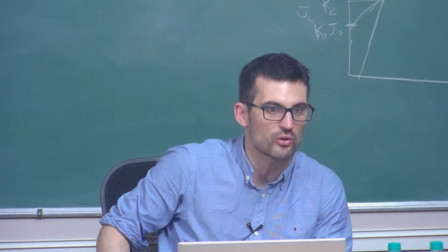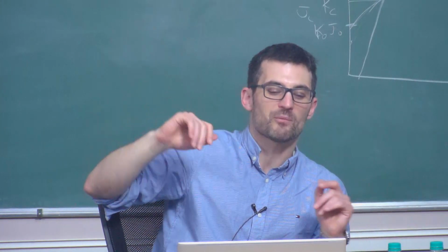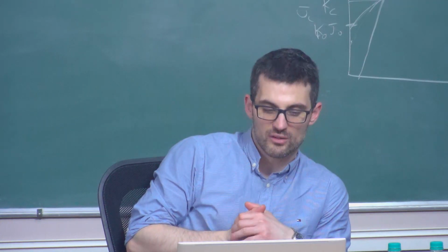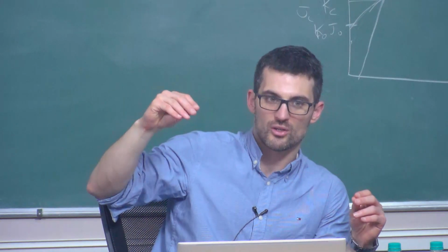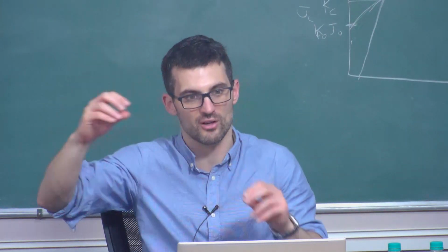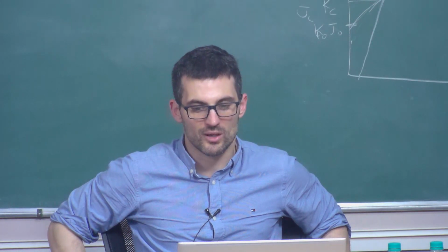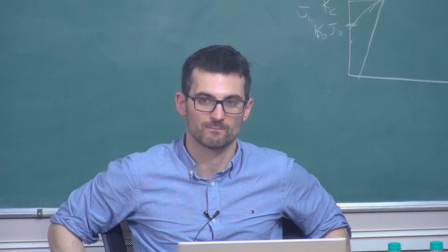I think in general, if you're talking about fracture in elastoplastic materials, this works okay, not only for small-scale yielding, where K dominates, but also for J. If you are talking about shear band localization, things like this, I think these other methods where the plastic strain lowers the fracture energy seem to do a slightly better job. So if instead of fracture you're thinking of more localization phenomena, it works a bit better in this other way. Maybe I could include a slide on future days to show what other people are doing. So there are various approaches.